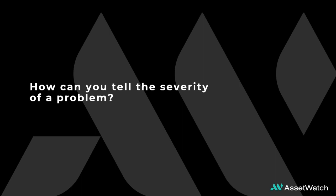Now, if you're looking at 0.9 inches per second in a bearing frequency, well, that thing's going to destroy itself really, really fast, and it's all relative to the speed as well. If you got a rotor that's turning 900 RPM versus a rotor that's turning 3,600 RPM, I mean, obviously the faster rotor is gonna tear itself apart, depending on what type of fault you have. So the severity really comes down to the amplitude and what type of fault is it, based off of what you're seeing in the vibration data at what frequency.